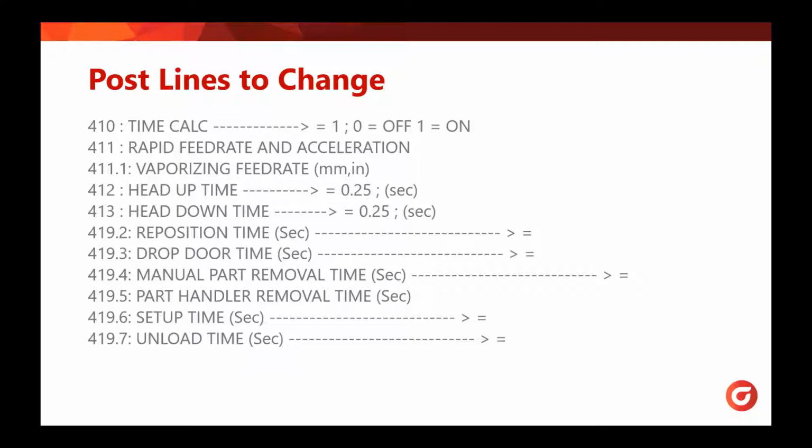So how long does it take to put the sheet on the bed, to load it, start the program. And then your unload time, how long does it take to get the sheet off the bed so you can start your next job. All of these are going to be estimations. Of course, we don't expect you to have accurate numbers for this every single time, but just a rough estimate will be good enough for this. There are other options inside of here, depending on your machine, but these are going to be the most common ones that you're going to see.